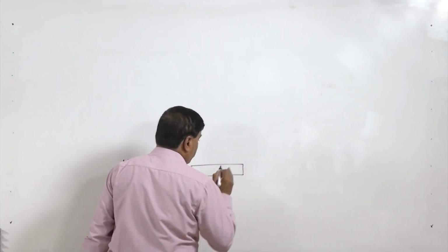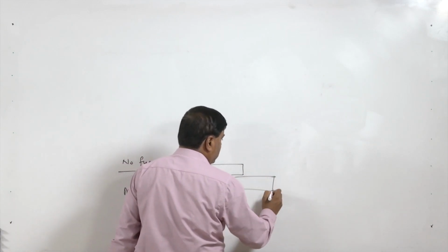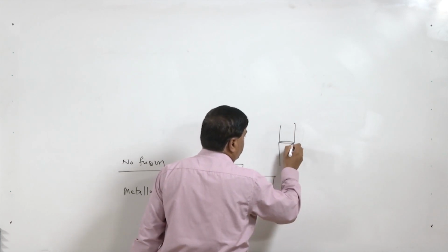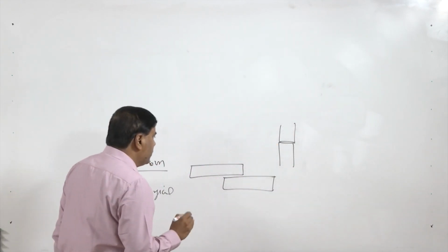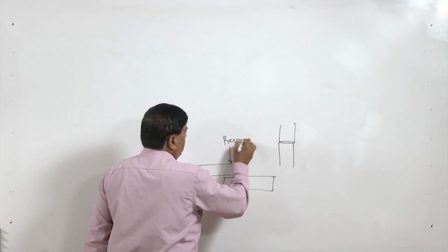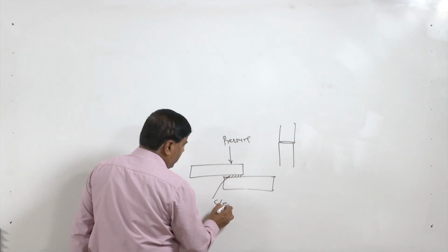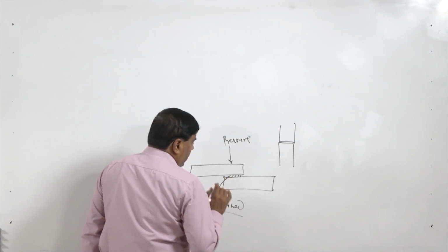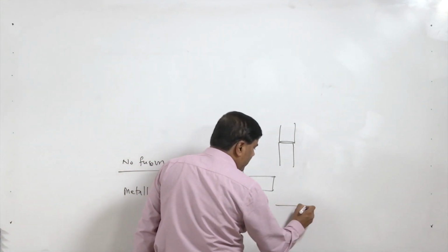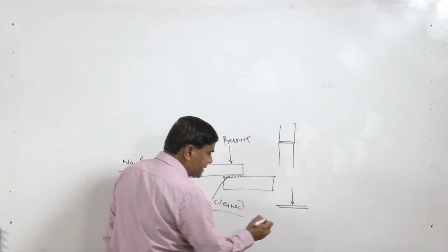Whatever type of the process we take, like the two components to be joined together in overlap joint configuration or in the butt joint configuration, we need to apply sufficient pressure, and the surfaces to be joined must be cleaned so that there is a direct metal to metal contact, and application of the pressure brings them close enough.